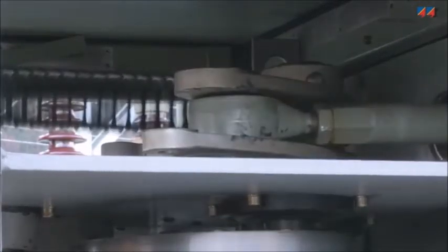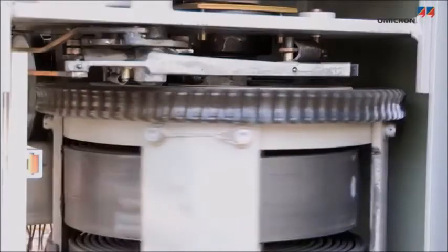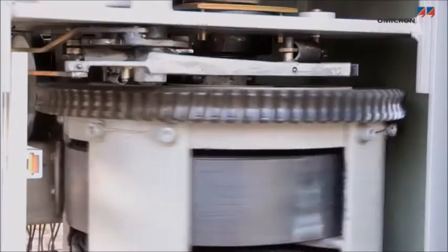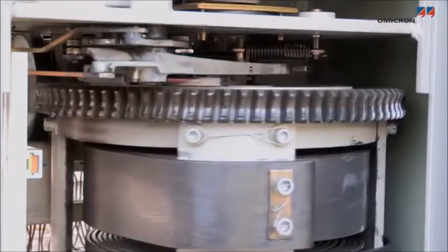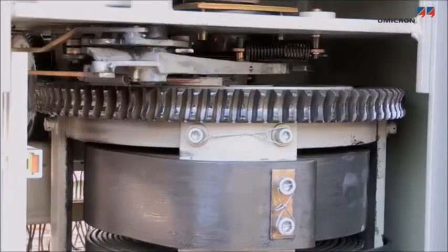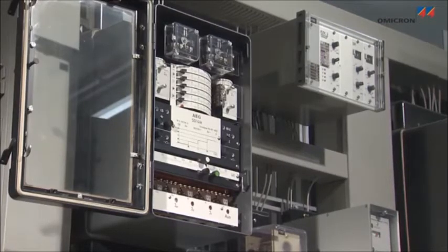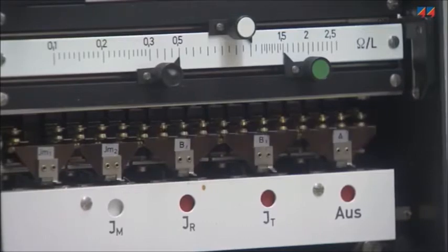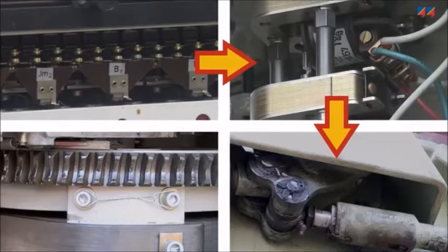The energy that opens and closes the contacts is typically stored in a spring, hydraulic, or pneumatic device or system. The stored energy is released by the trip or the close command signal. The command signal activates the trip and close coils, releasing the drive mechanism to perform the opening and closing operation.